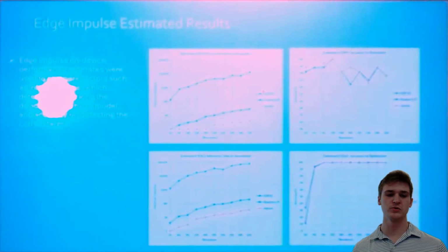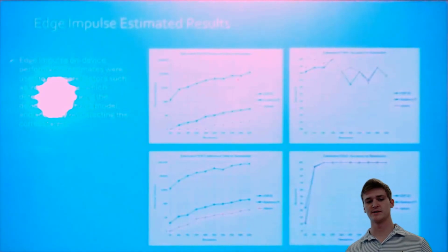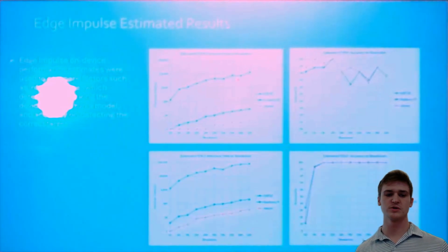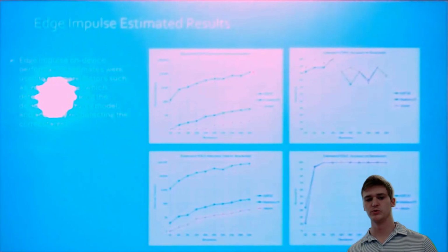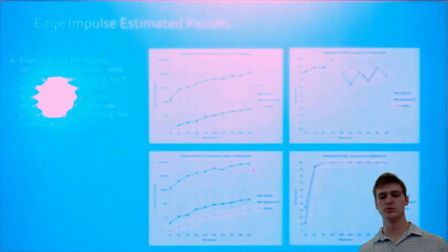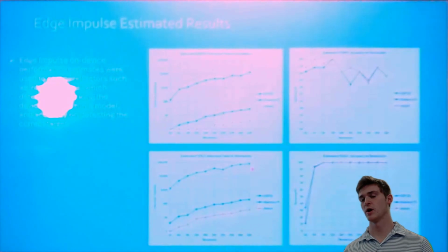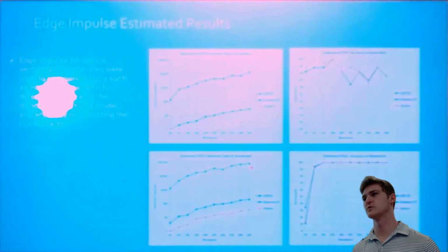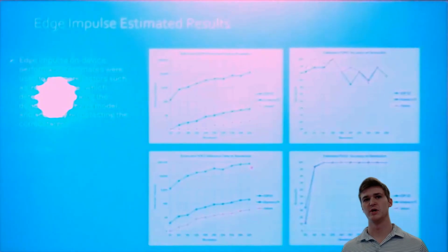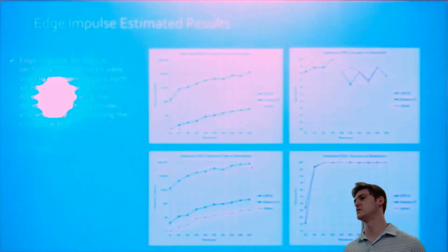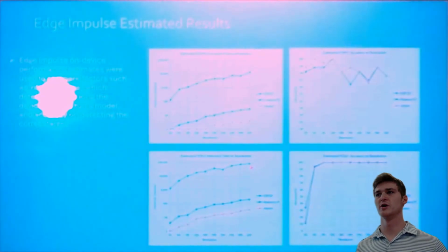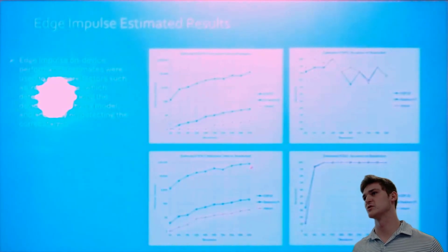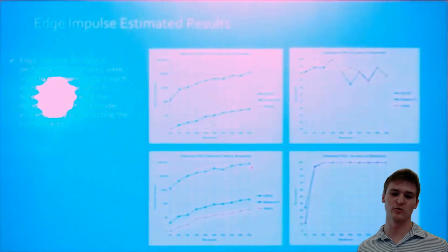The ESP32 with increasing resolution quickly got to crazy inference times. For FOMO models, up to 10 seconds for 320 resolution, and YOLO up to close to 100 seconds for 320 resolution, which is really just impractical for the competition setting. You need to be able to accomplish tasks in a timely manner. The time limit is 15 minutes for the RoboSub run, so if you're standing there for a minute trying to detect one target, you're going to be in trouble overall.